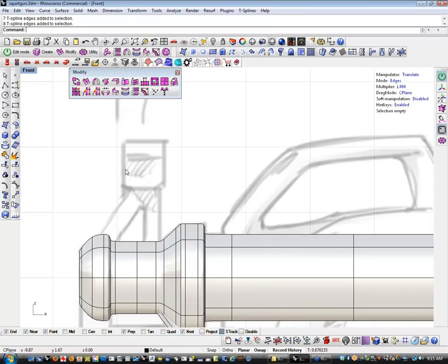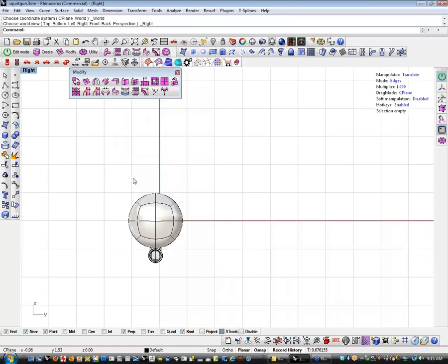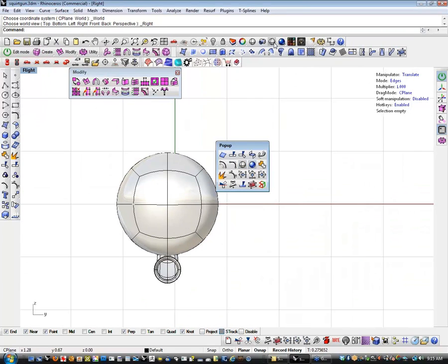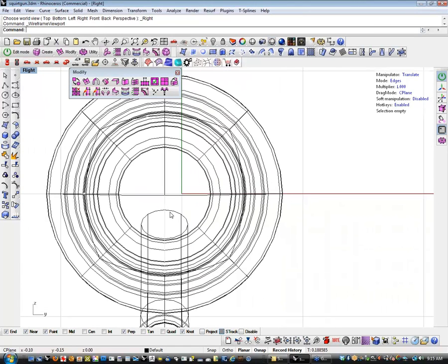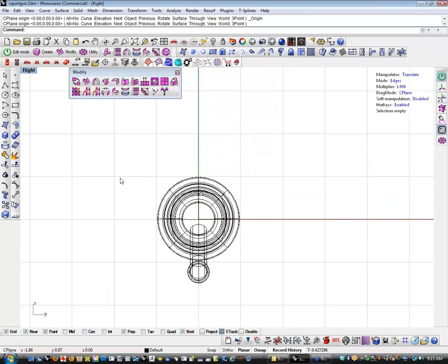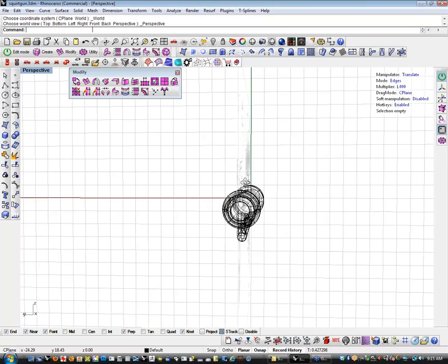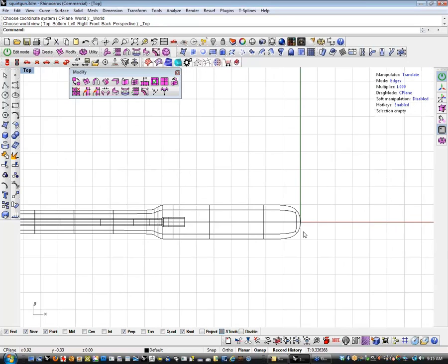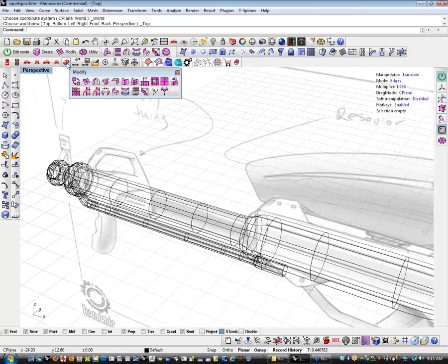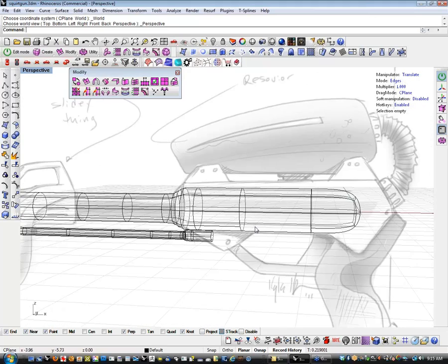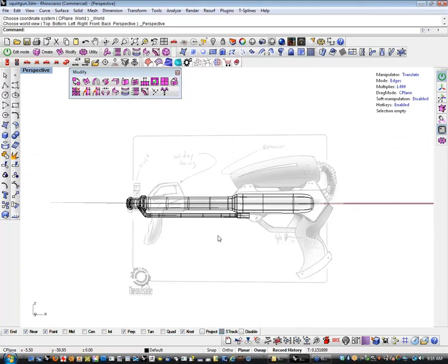So I'm going to go after all the easy gets on this so far, and we will throw, let's see, it's going to the front or rear view, doesn't matter. We're not in the origin. That's not good. Let me reset my origin on my plane here. That's not right. I want that centered there, so I should be on my origin. Just checking the top view here real quick, make sure that we're lined up. Yeah, okay, that's better. The way I did that was I just reset the set C-plane origin using the Rhino tool up at the top there. Alrighty, so now we should be lined back up again.